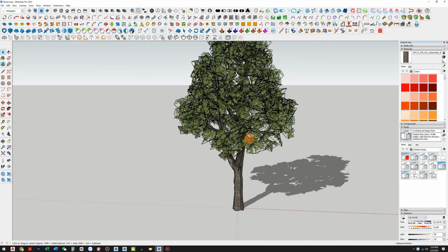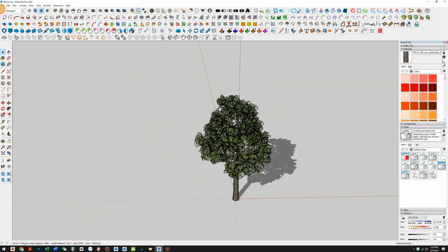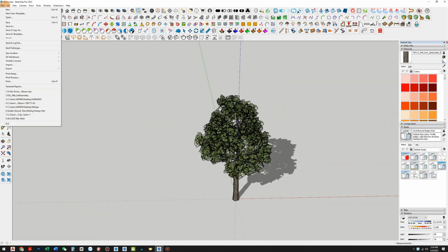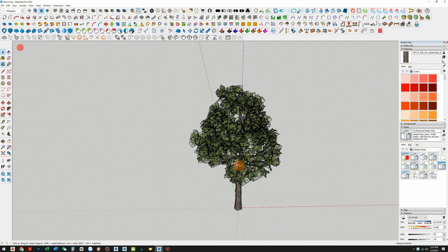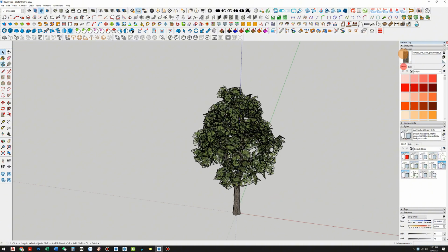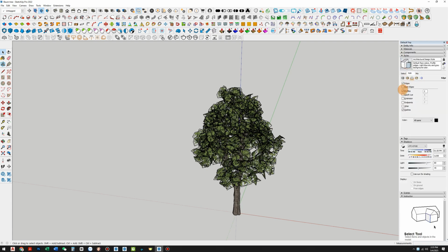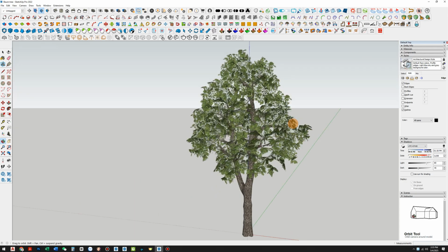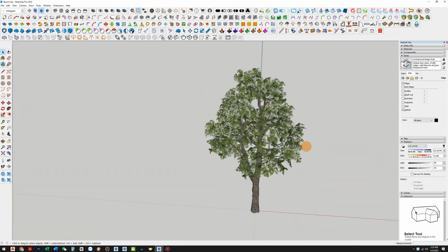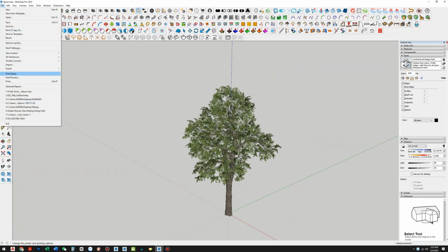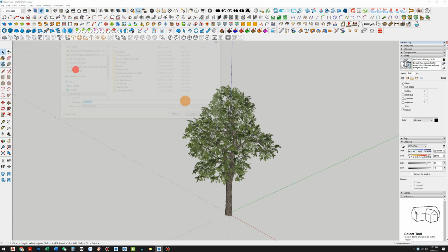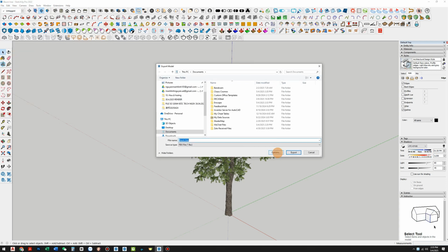Step 1. Convert your current file to FBX format. First, we need to check and ensure that your SketchUp model is complete and free of any issues. Double-check all objects and make sure everything is properly adjusted. Next, go to the File menu, select Export, and then choose 3D Model. A window will pop up where you need to select all the necessary export options and set the unit to meters to ensure the scale is correct when converting to Enscape.